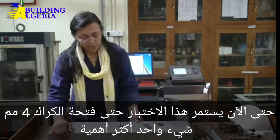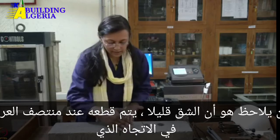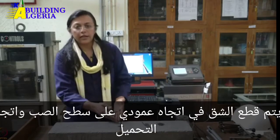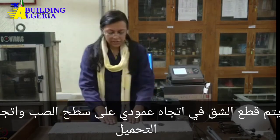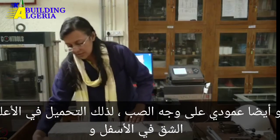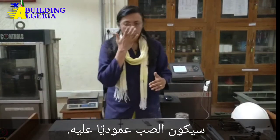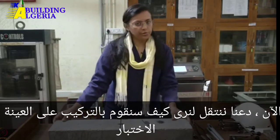One more important thing to be noticed is that the notch is cut at the mid width in the direction which is perpendicular to the casting face. This is the casting face of the specimen, and the notch is cut in a direction perpendicular to the casting surface, and the loading direction is also perpendicular to the casting face. So loading on top, notch on the bottom, and casting will be perpendicular to it. Now let's move on to see how we are going to mount the specimen onto the testing frame.